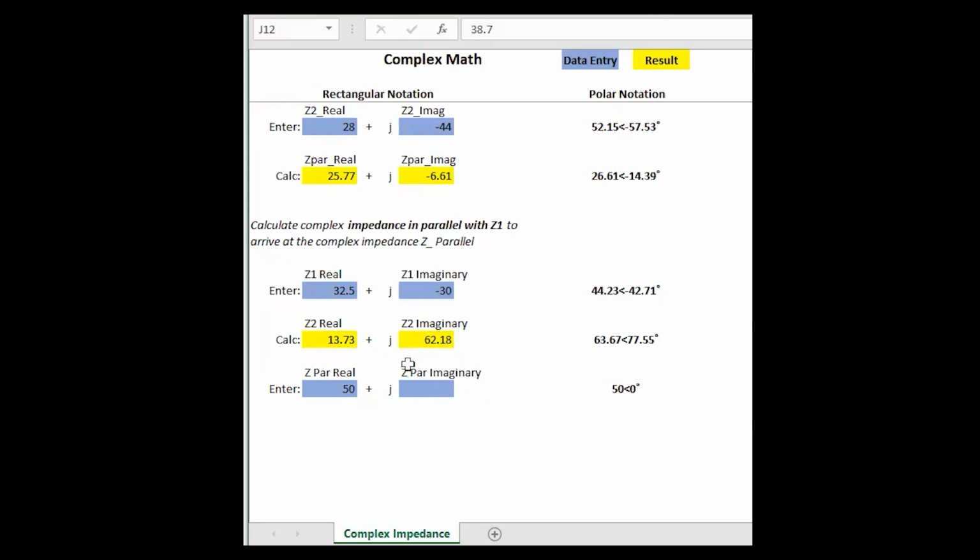That's the number I'm going to want to work on in our next presentation on the Smith charts. That's the number I'm going to want to try and incorporate into my shunt. And so knowing where to put that spot on my Smith chart, then I'll be able to work around how many degrees in length and whether it's open or shorted at the end of my coax or twin lead or whatever it is I've got.